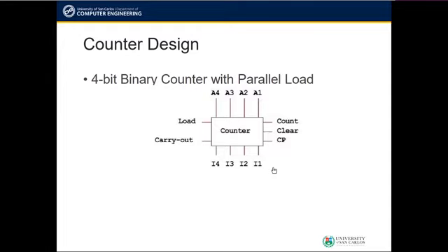The counter counts from 0000 to 1111 and repeats the count starting back from 0000 after the last count of 1111. Again, remember that this is not yet an actual MSI IC, and we shall use this block diagram to explore some common functionalities and behaviors of counter ICs.